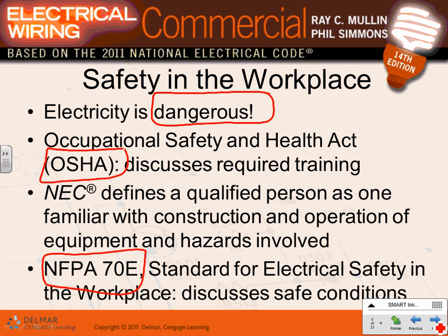Mostly the arc flash is a big deal. So when you work around electrical equipment as a designer, the rule of thumb from OSHA, 70E, and good practices requires that if this is a panel and an electrician is hired to work on it, you move 10 feet away. That's the safest boundary for arc flash. Typically the arc flash danger is within a couple of feet of it. The safest point is to move at least 10 feet away from the place where people are working. If you don't do the calculation, your arc flash boundary, as they call it, is 5 feet.